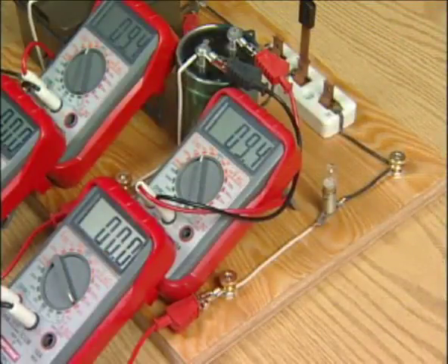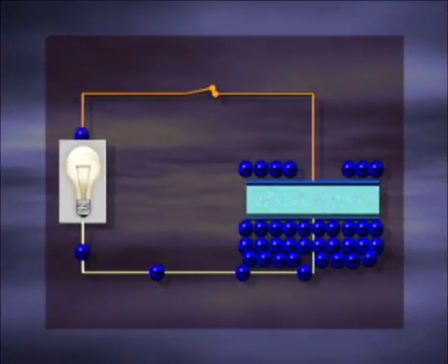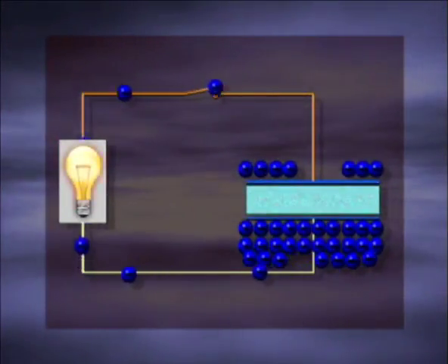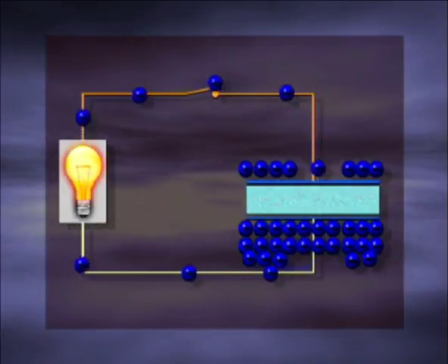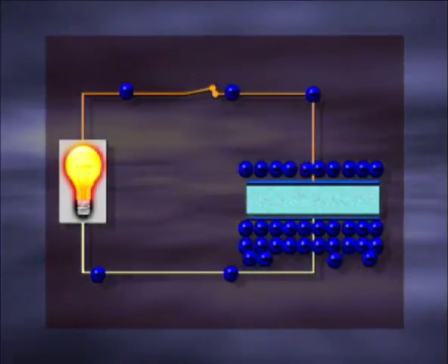The action of recovering the energy stored in a charged capacitor is called discharging. In order to discharge a capacitor, there must be a complete circuit between the capacitor plates. During discharge, the surplus free electrons on the negative charged plate flow toward the positive charged plate through the discharge path.